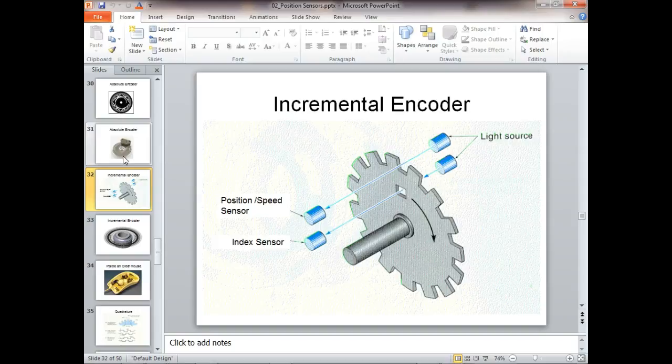Now, robots use something unique in that they call them absolute encoders, but they're not. If you looked at the technical information on robot encoders, they're called battery backed up absolute encoders. So when you go out and buy an encoder for a robot, it comes in an assembly, and it's got the incremental encoder and the counters inside the encoder. So the counters are inside the encoder. So when it comes out of that incremental encoder, it looks like it's an absolute encoder, but it's not.